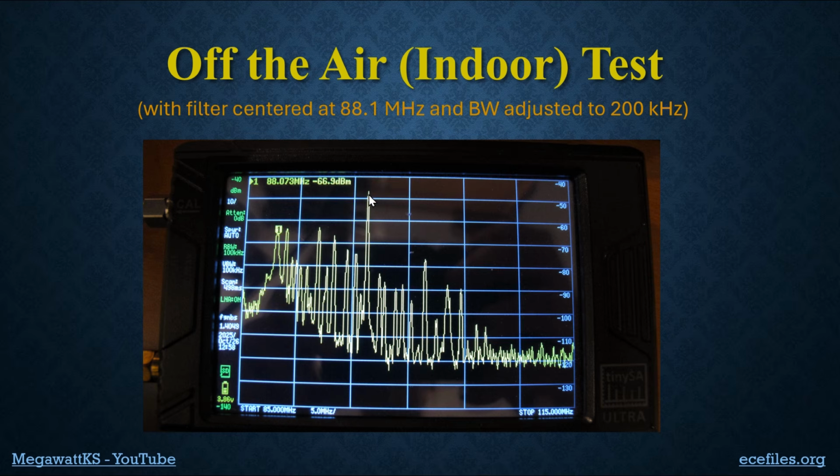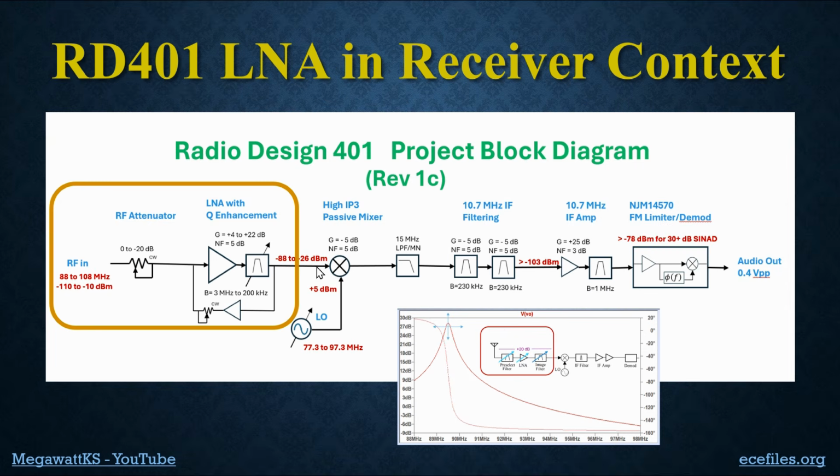Meanwhile, the minus 30 dBm signal is now down close to minus 50, minus 48, something like that. So the strong signal has not only not been amplified, it's actually been attenuated from what it was before, whereas this one is amplified by 20 dB. This is exactly what we want, because we don't want these strong signals to go downstream in the receiver and hit the mixer and other stuff and cause intermods. That could happen here at the mixer if we didn't take actions in the LNA/filtering to prevent it.